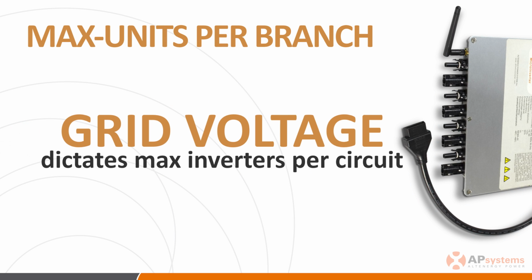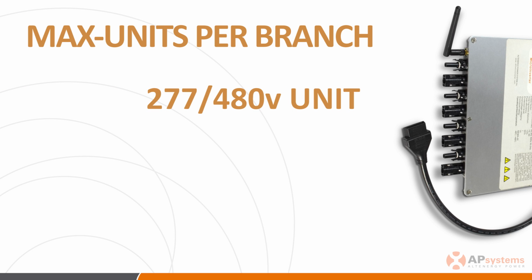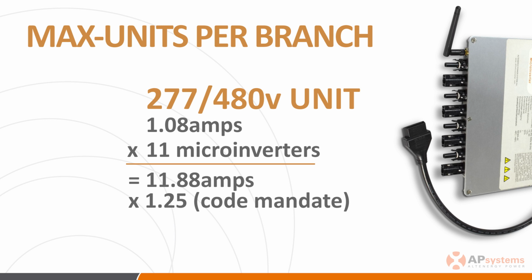The maximum number of YC1000 inverters per circuit is based on the amperage produced by each of the units. For example, in the case of the 277/480 volt units, each inverter is spec'd at 1.08 amps per phase. Multiplying the 1.08 amps times 11 equals 11.88 amps, and multiplying that result by the code-mandated 1.25 equals 14.85 amps per phase, which is under the 15 amp circuit sizing.